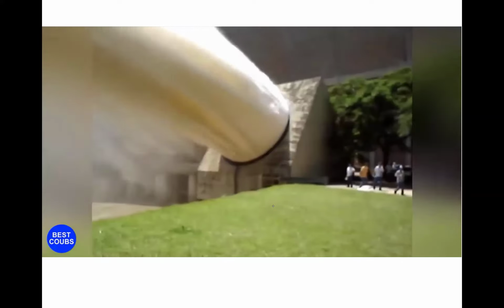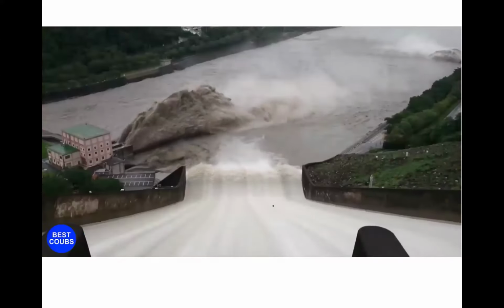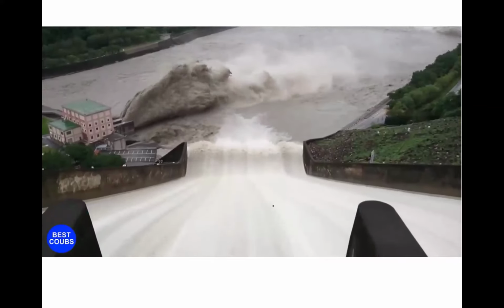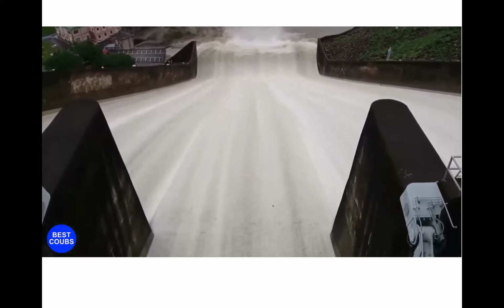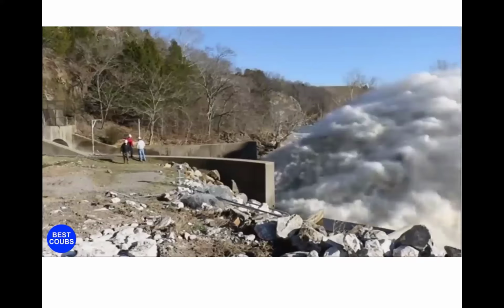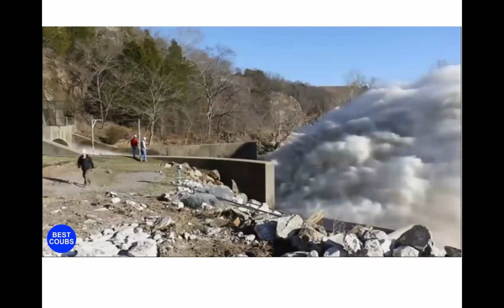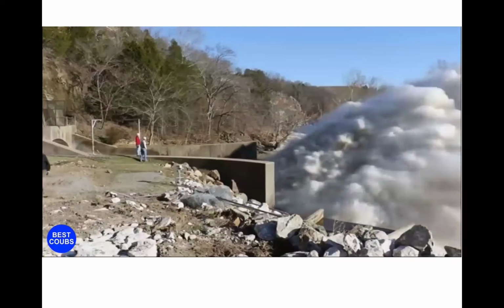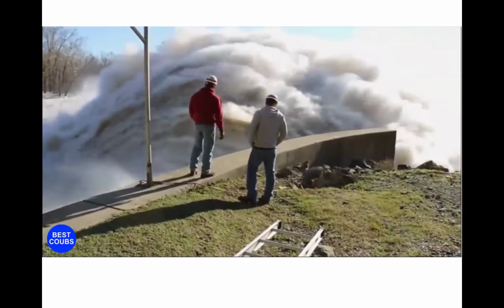This is another jet coming out of an outlet. Again, look at the people and the dimensions of the jet. This is probably like 10 meters in diameter or something around there. Enormous jet. This is another flow looking down at the spillway chute. Again, it doesn't have that typical hydraulic jump. These are called flip bucket or ski jump type structures. So they basically discharge the jet into air. This one the same, and let the air do the job really to dissipate. This is another view. Again, an enormous amount of flow at extremely high velocities coming out.